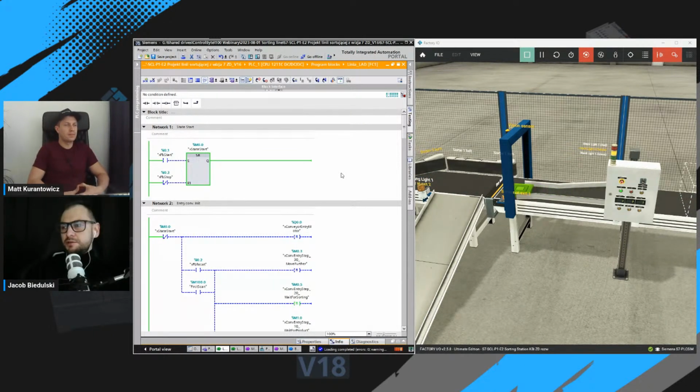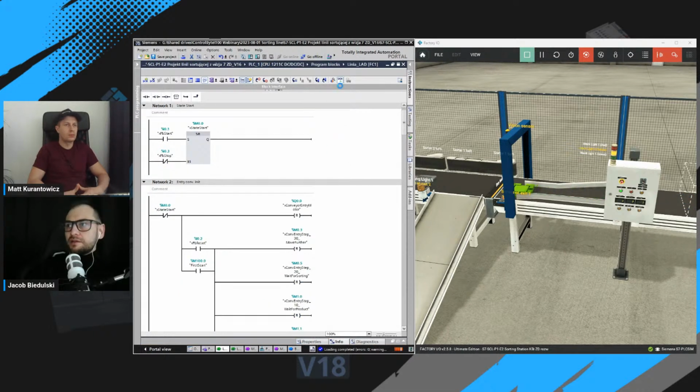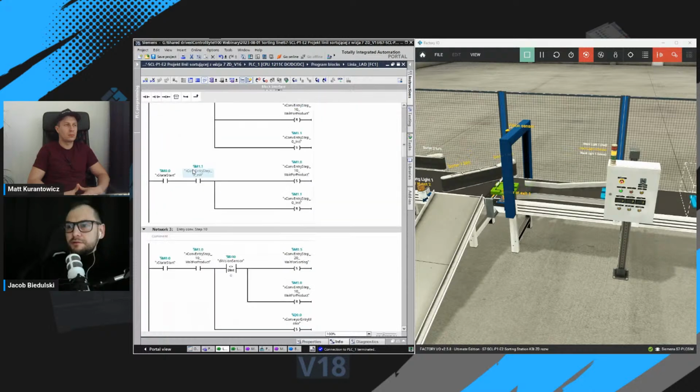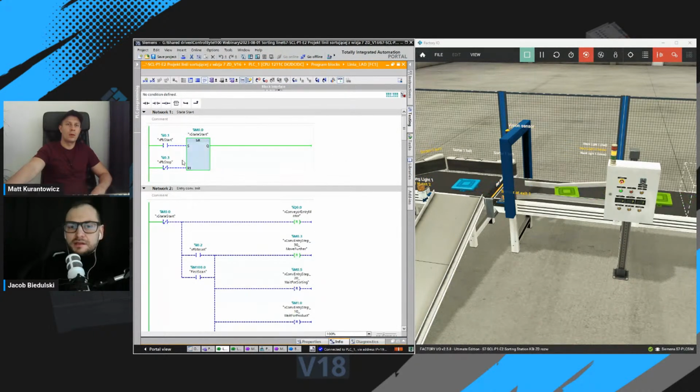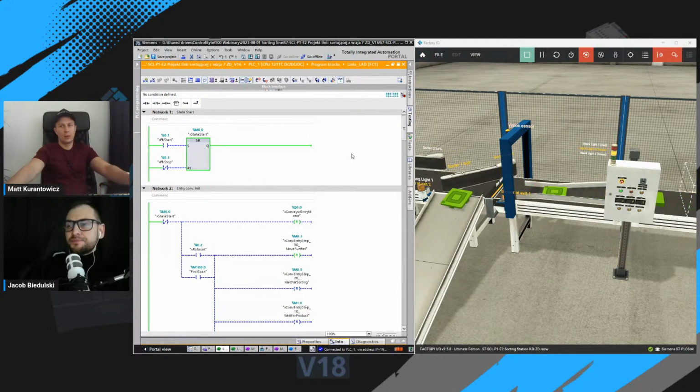Okay. So why should you start with ladder logic? It is easy to understand. Here I have the online view. This is the offline view. Everything is black, white, and gray. If I go to the online view, some of the structure, some of the code is highlighted in green. The green highlight means that in this section we have logical 1.